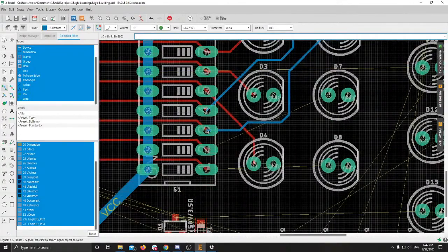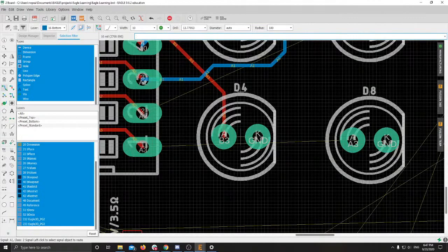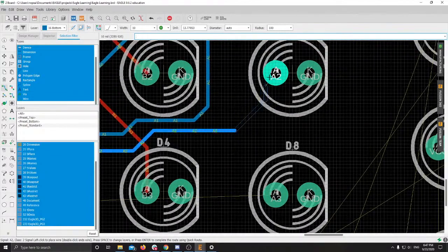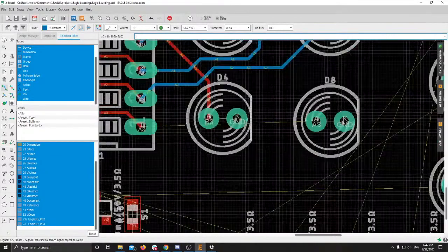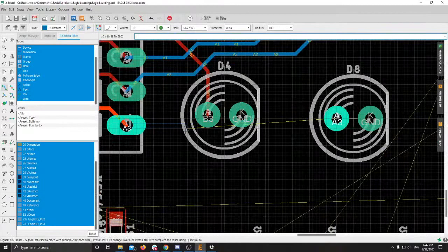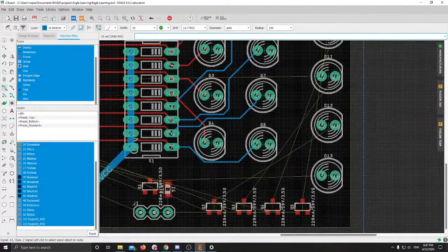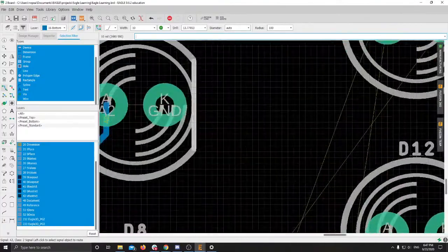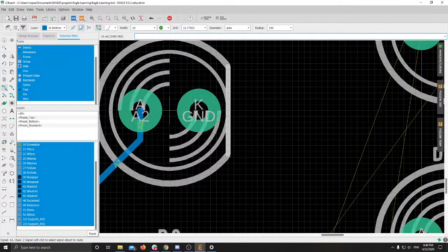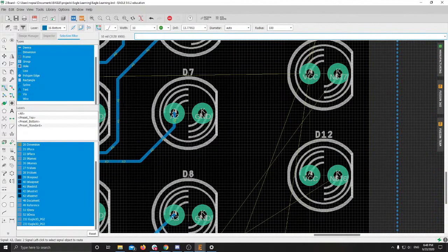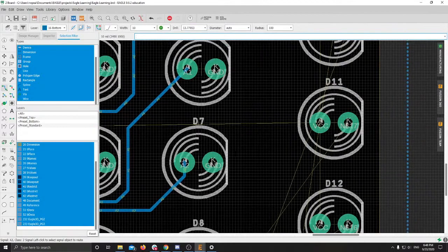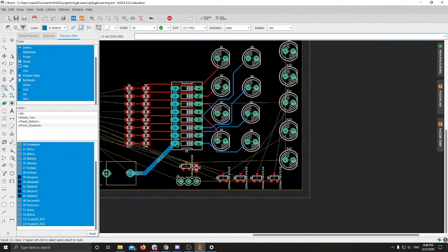Do something like that. Here, luckily, we can just avoid doing it to begin with, and ta-da, that's all done. Now you'll notice we don't have to route the other side of the LEDs because they're already connected to ground, and that'll be done for us by the ground plane, which is rather convenient.